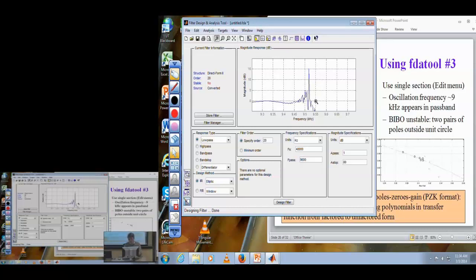You start with all the poles and zeros in double precision float. You expand them out, and each multiply, you lose 53 bits of mantissa, because you're keeping everything in double precision float. We had this discussion in an earlier lecture. So you end up with the feed-forward coefficients have a lot of error in them, because you're not doing the expansion in exact precision.